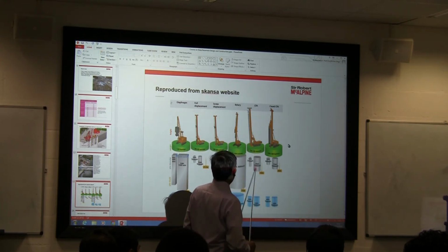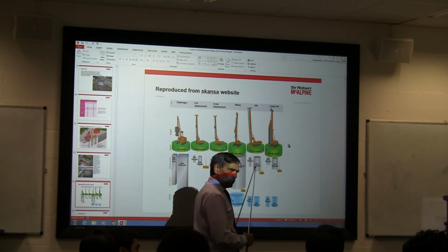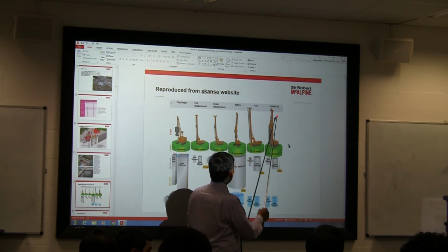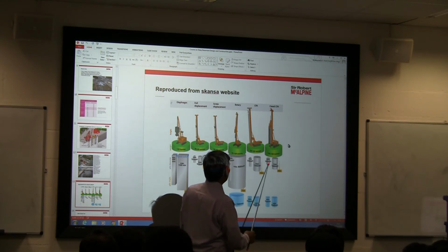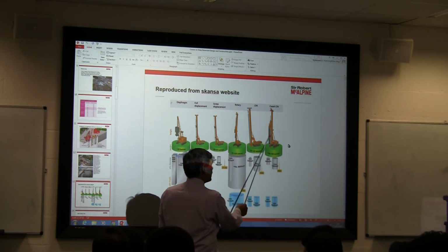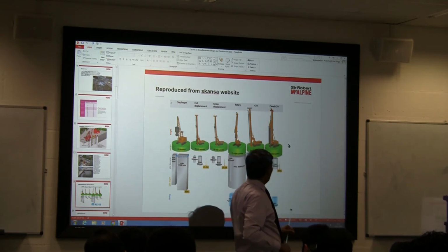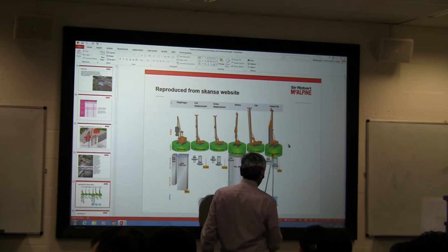And then in the CFA piles, you can see maximum 32 meters, minimum diameter 350, maximum you can go up to 1200. And if you are using a cased CFA, the minimum is 600, 1000. Again, you are limited by the auger, which is the length of the auger that can go 26 meters. Can't go beyond that.